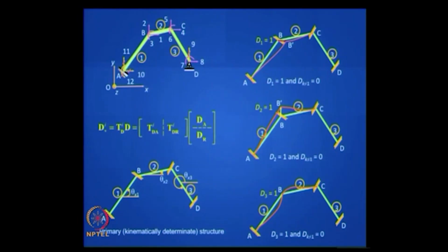You can actually do it from first principles using the physical approach, because we did a few examples earlier, right? But the computer has no feel for any physical approach, it has to do it mechanically, blindly, and that too is possible. Before that, let me talk of this matrix K star, which is sometimes referred to as the unassembled stiffness matrix.